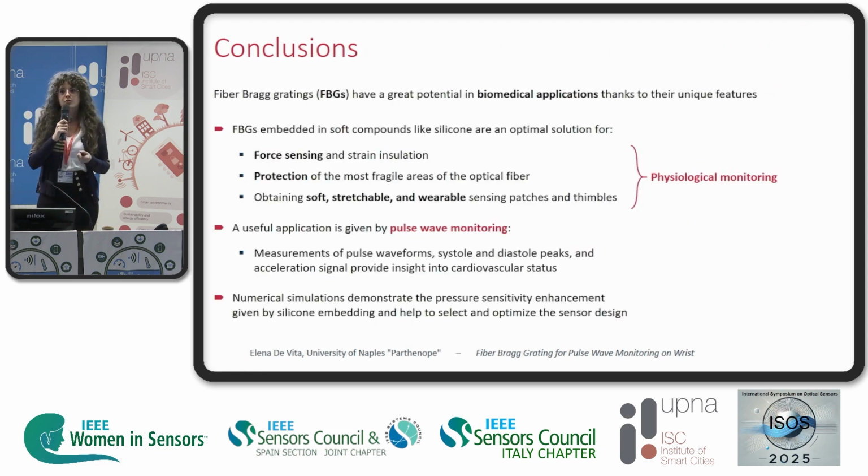So to conclude, we can say that fiber Bragg gratings show great potential for biomedical applications. And if we embed the FBG in soft compounds, we can have soft sensors, but also stretchable, wearable, and we can make them sensitive to force, to transversal force and pressure.